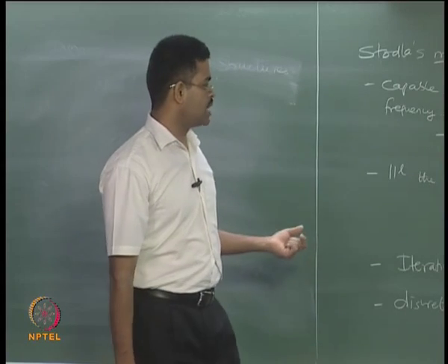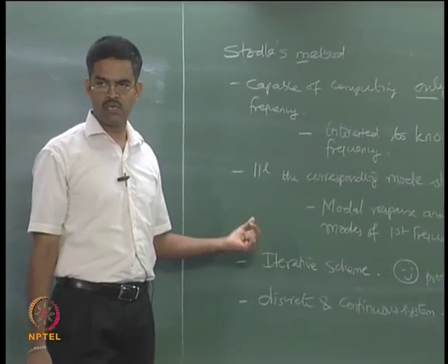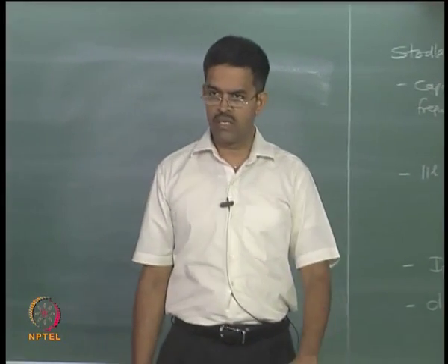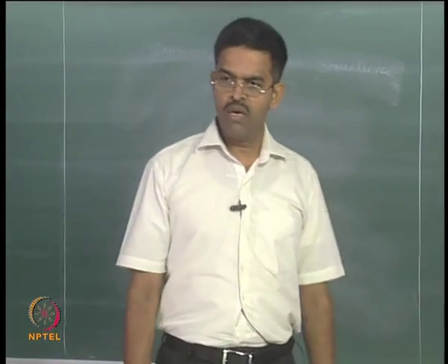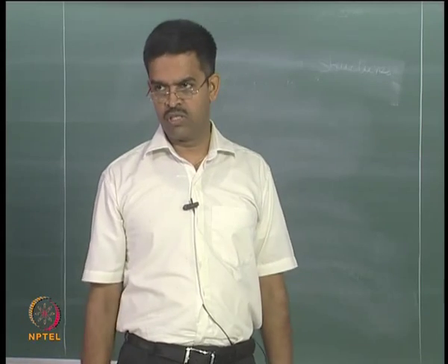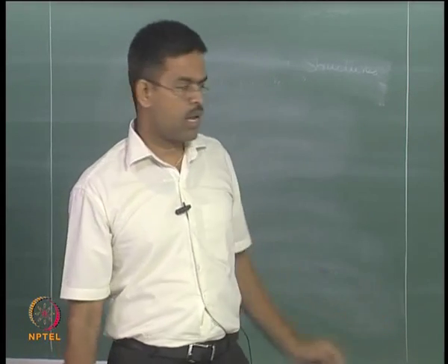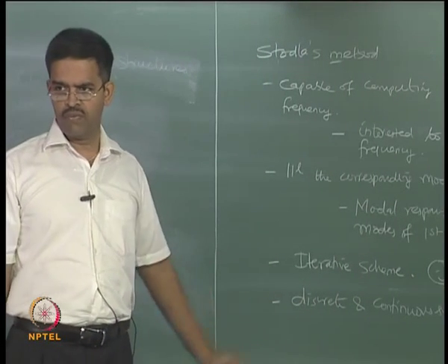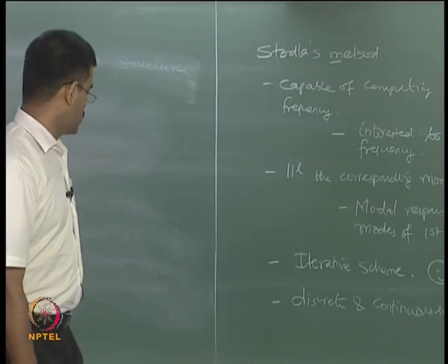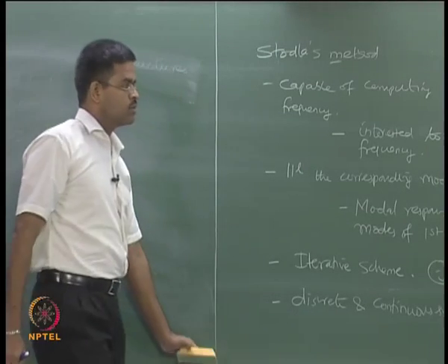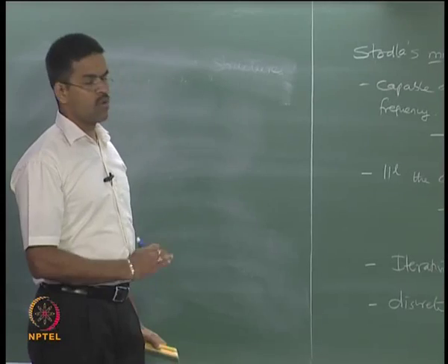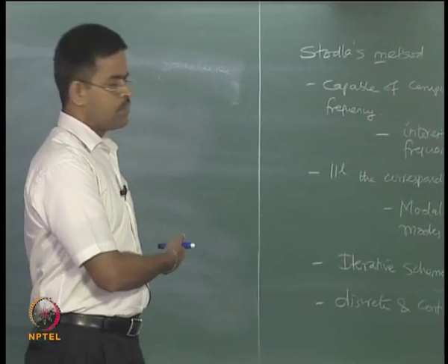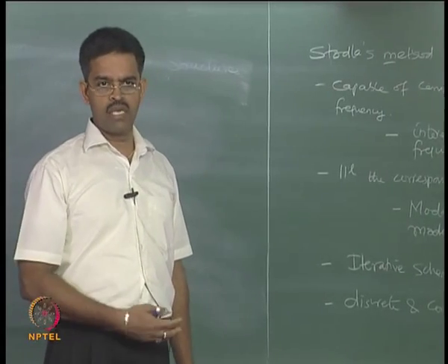So, there may be a small catch here in how to write the alpha coefficient matrix for the given multi degree freedom system. We have already seen in previous examples how to write the stiffness matrix directly by giving unit displacement and getting the forces. We have done a couple of problems. Here we are applying unit force and getting the displacements, that is the influence. So we are trying to find this by a slightly different technique today. Closely follow this. If you are able to follow this technique of estimating the influence coefficient matrix, it will be useful for you to solve the problem for omega and phi as well as write the equations of motion.